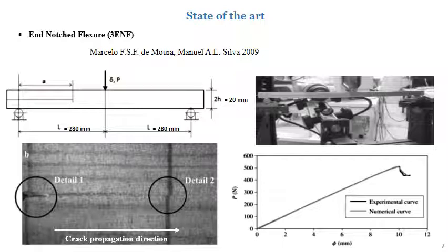To measure the length of the crack during propagation, a scale was marked on one of the edges of the specimen. However, it was quickly concluded that significant errors were made due to the uncertain identification of the crack bottom. In the figure, a discontinuity can be observed on the second black vertical reference line, detail 2. However, the position of the tip of the crack could not be defined because practically no change is evident in the second edge of the specimen. Furthermore, it cannot be ensured that this discontinuity on the black line corresponds to a continuity of crack propagation.